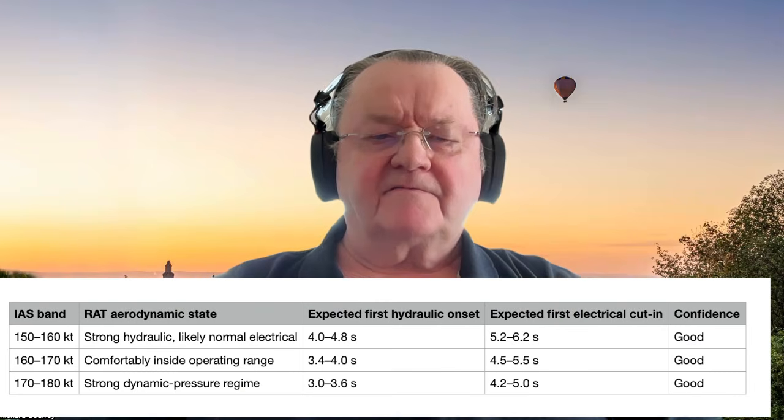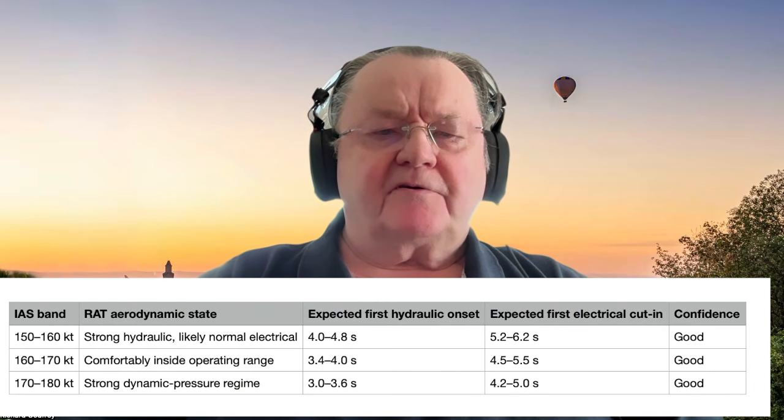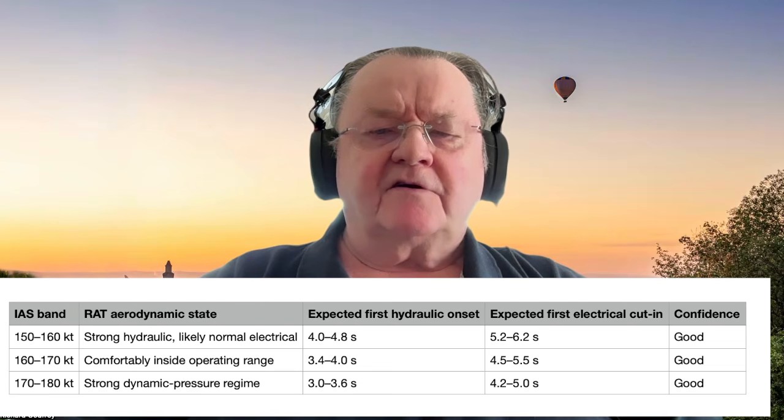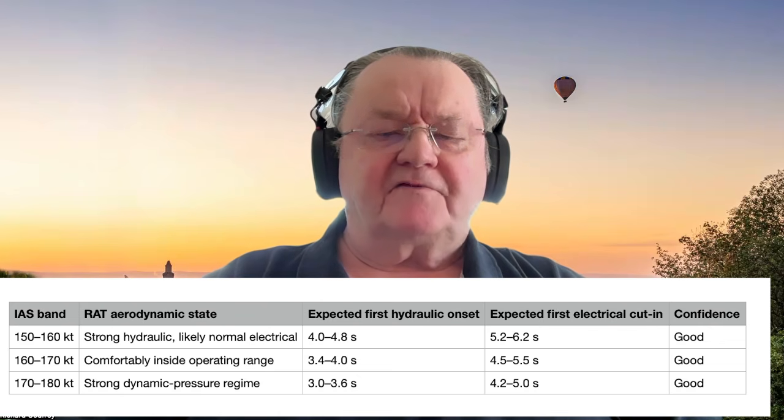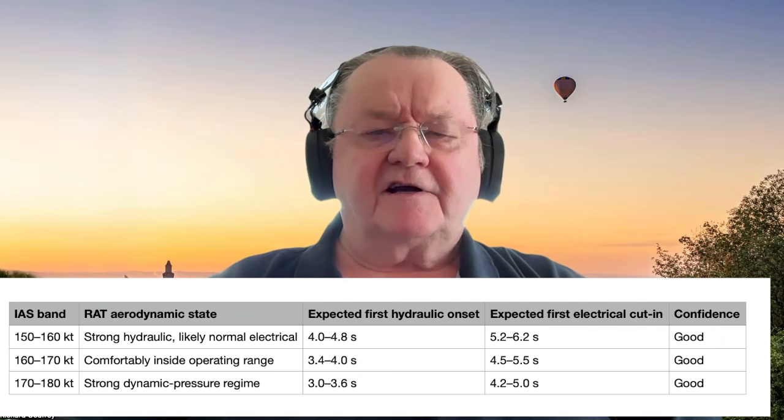An airspeed determined from all three corrected airspeed parameters delivered via the core data network, and the VFSG speed is determined from each of its generator controller units. RAT auto-deploy is inhibited when not in the air mode. In other words, at least 80 knots of airspeed or any of the VFSGs has moved from starter mode to generator mode.